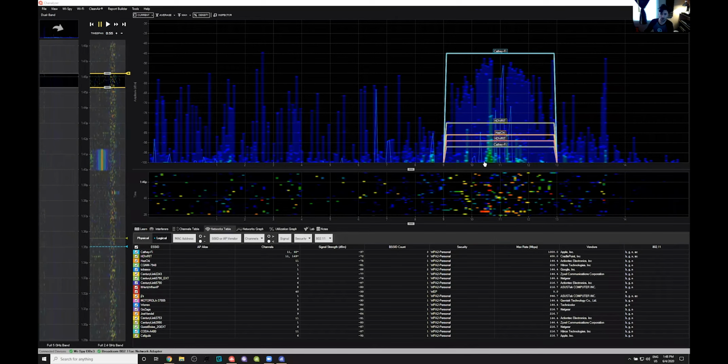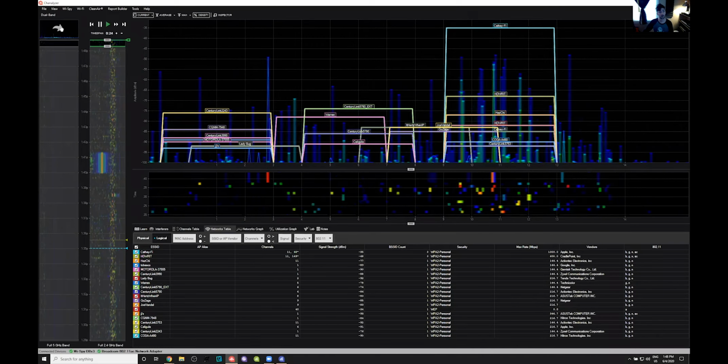Can Channelizer be used to analyze airtime usage? In terms of spectrum, absolutely. I think spectrum is kind of the say-all. You can kind of get a good idea of airtime with packets and packet analyzers, which of course MetaGeek sells with other products like Insider and IPA. But a true measurement of airtime is, in my opinion, a spectrum analyzer.